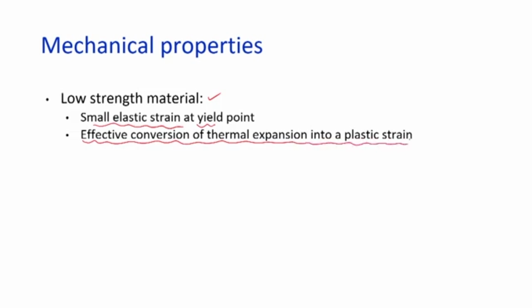If the material has low strength, we can easily deform it, and the same is useful for the laser bending operation as well. That is why low strength material has more ease of deformation in laser bending.